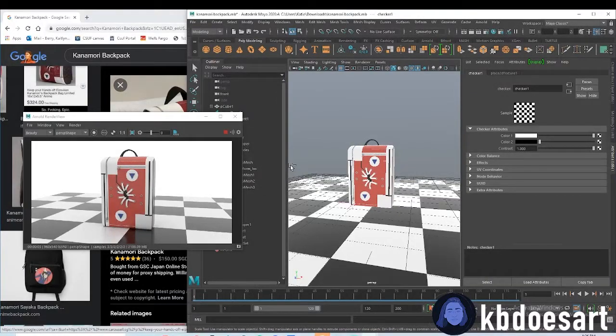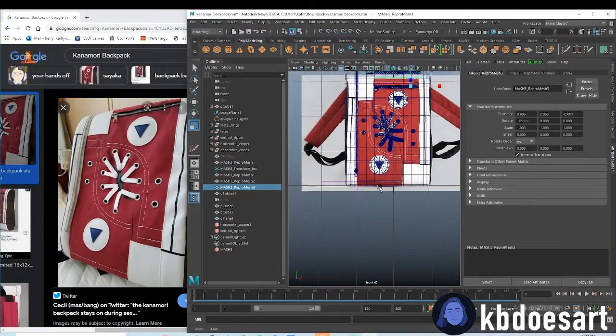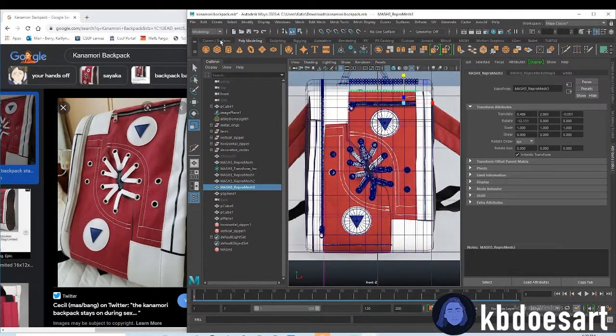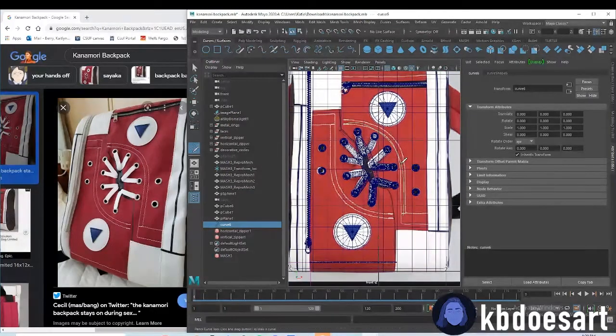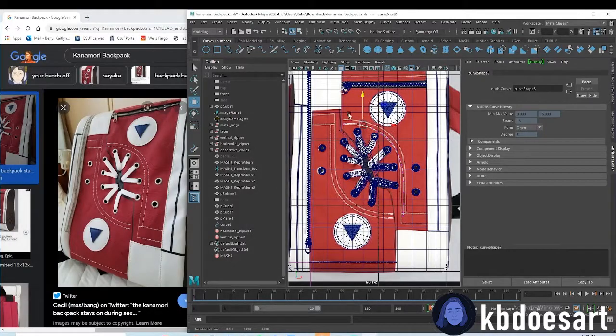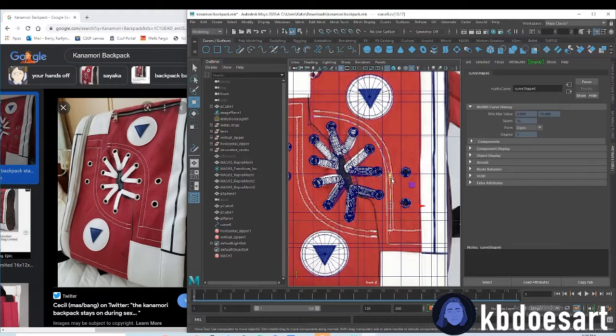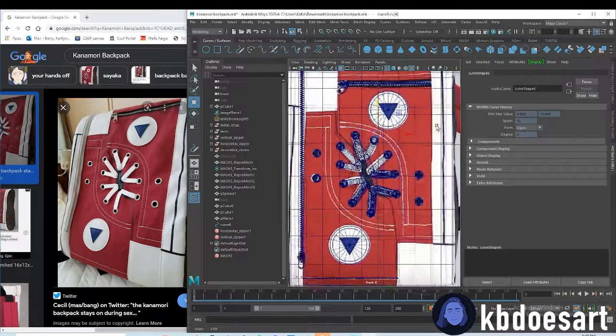All right, so I'm gonna finish up the seams because I think that'll help tie it together. All right, so let's first do the curve. So go into front-facing mode and just go to curves and surfaces, and you're going to draw a curve to the best of your ability. And then click Q, do control vertex, and edit them to the best of your ability to fit that guy. Okay, looking good.